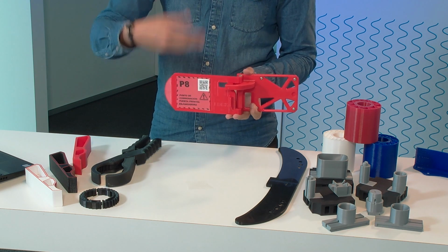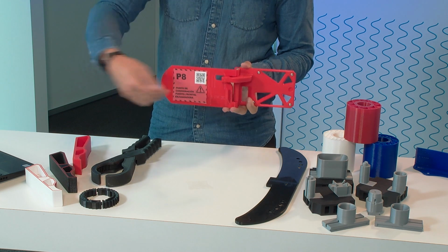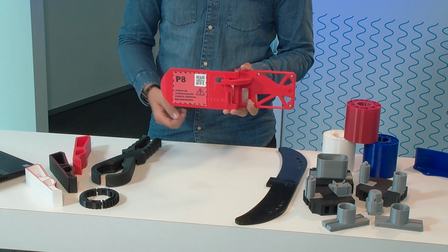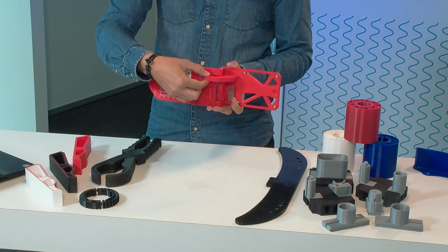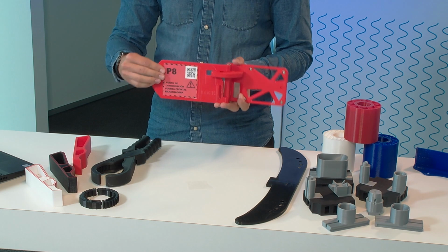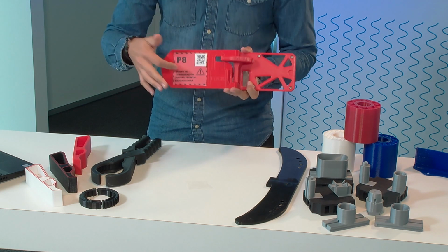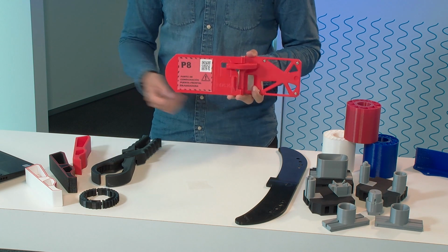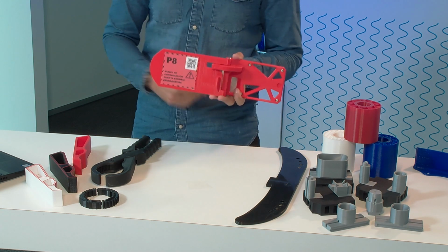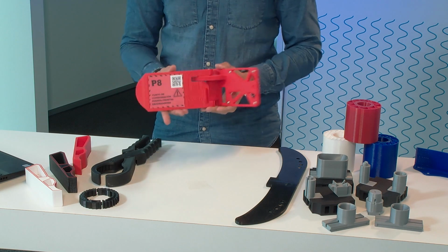If it closes, then the machine knows, okay, I can run. But if you obstruct that with this, for example, it cannot enable itself. So you put the padlock here again, so you know that it's locked and cannot be enabled. On this side, you see a red indication, also that the LOTO has been applied and you cannot run the machine. So this is really something safe.